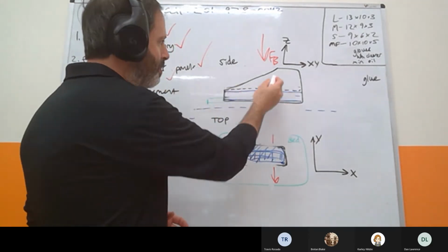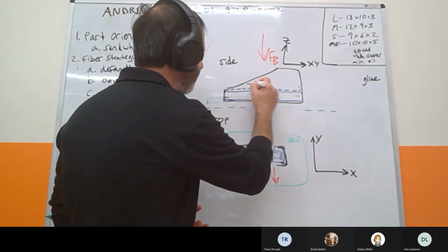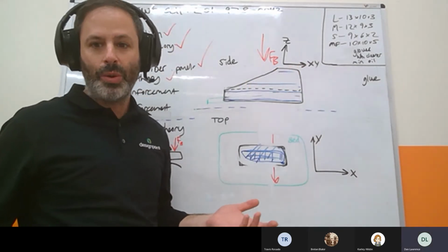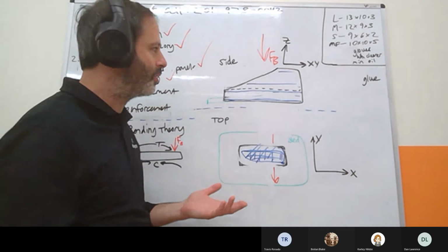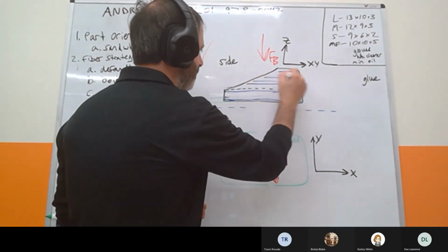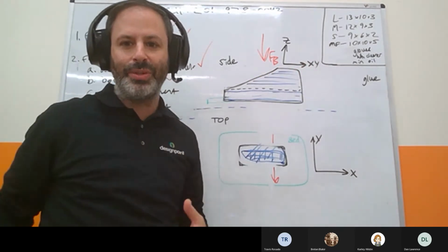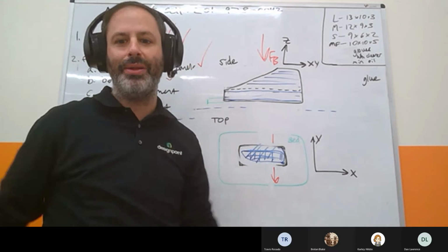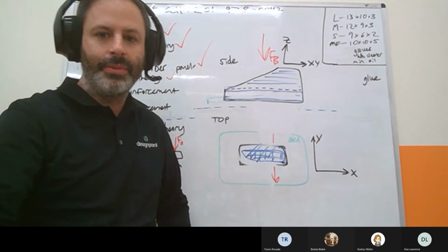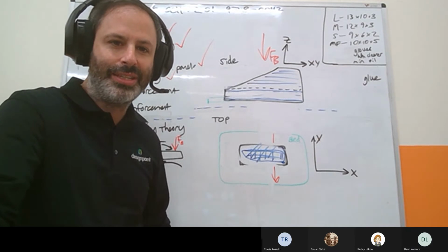But when I come up into this top part, I can't do that anymore. Because if I do a panel down here and a panel up here, now I have an imbalance. So one thing you might do in this situation is the fiber striping, and you kind of keep adding them as you go, so it doesn't have such a big imbalance. It kind of builds that way. So that's how I would use fiber striping. Dan, any thoughts on that?